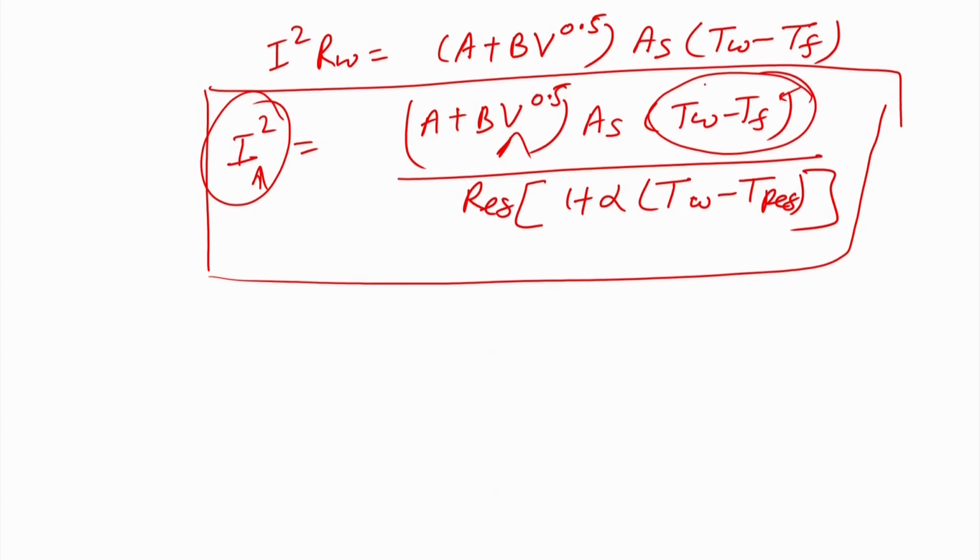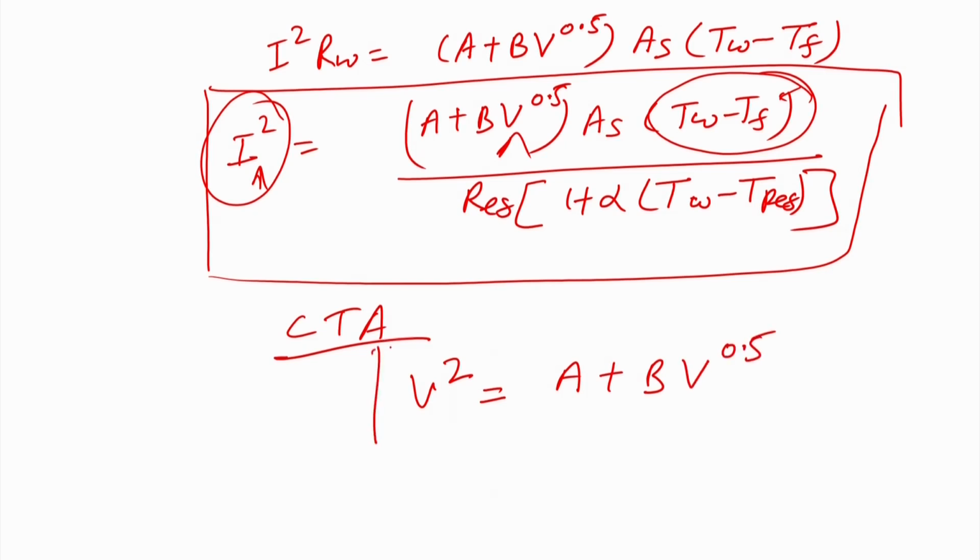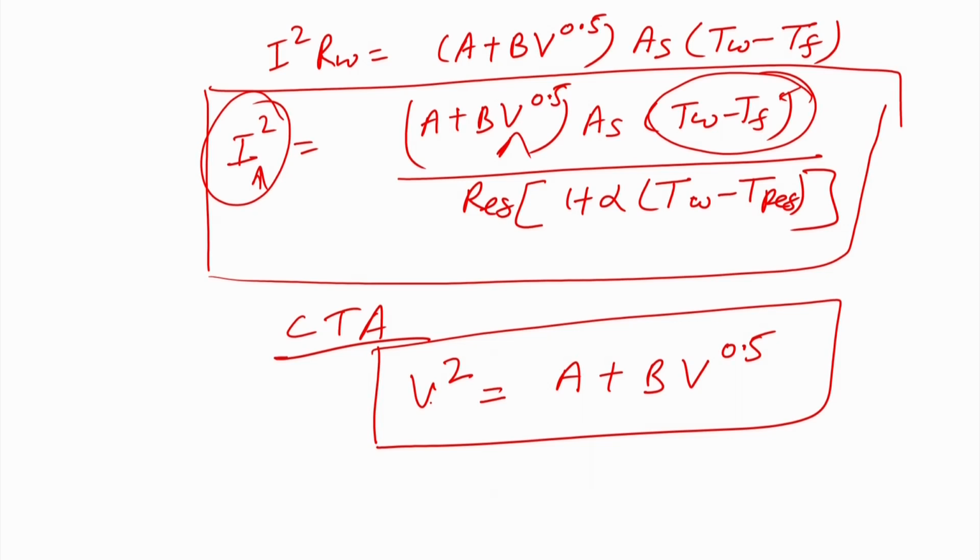Okay. So, the temperature will be constant, and you can measure the correlation, you can measure the velocity, and the equation will be simplified, and you will get the velocity for, say, a constant temperature anemometer. Finally, you can write I in terms of V square. So, I square will be V square upon R square, this will be cancelled out, and it will simply be King's law, A plus B into V raised to the power 0.5. Here the V is volt, so I will not confuse it, I will write it as E square, where E is volt.